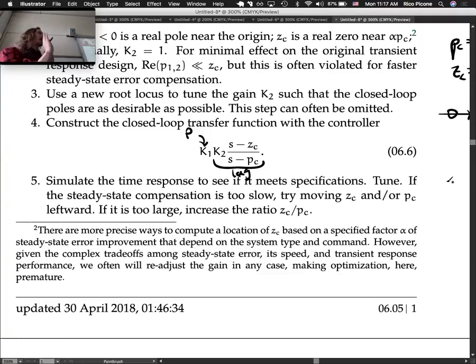So say you want that angle to be 30 degrees or whatever. You can measure the actual angle, maybe it's 20 degrees right now. You'd like it to be 30. You compare it to the reference. So there your reference is 30. The actual feedback output is 20. You take that error, the difference, and you feed it into your controller. So the way that actually works is you have your measurement, which is probably like a voltage, right? So you take your measurement, which comes from an encoder in the case of a motor, typically.